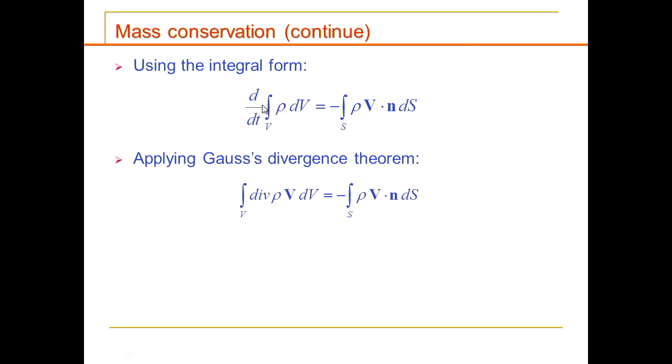Once we derive this formula, this is dm/dt, by the way, I'm being lazy. So mass equals density times volume. So integral of rho over volume V will give you rho times V, that is m. So this is dm/dt, but I skipped one step here. Another theory you need to introduce before we can derive the general form of the continuity or mass conservation equation. They are the same. Continuity equals mass conservation, by the way.